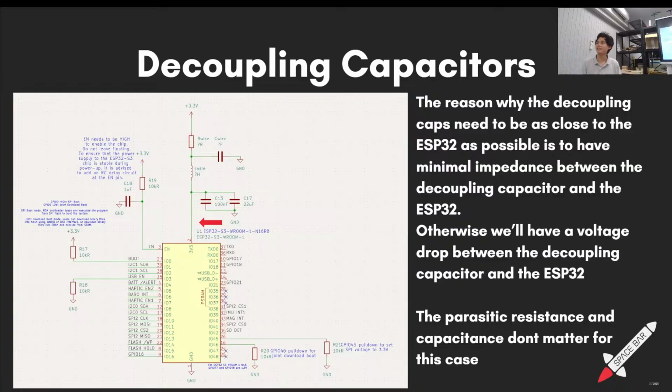Great. Okay, so what we would do is something very similar to this. We would have a single bulk decoupling capacitor for the entire chip, and then we would have 6 tiny decoupling capacitors, one placed close to each power pin. So each power pin will have its own tiny decoupling capacitor which absorbs the voltage drop for long enough for the bulk decoupling capacitor to overcome the impedance and get over here and fill in the rest. Does that make sense? So it's slightly damage control for the bulk one.